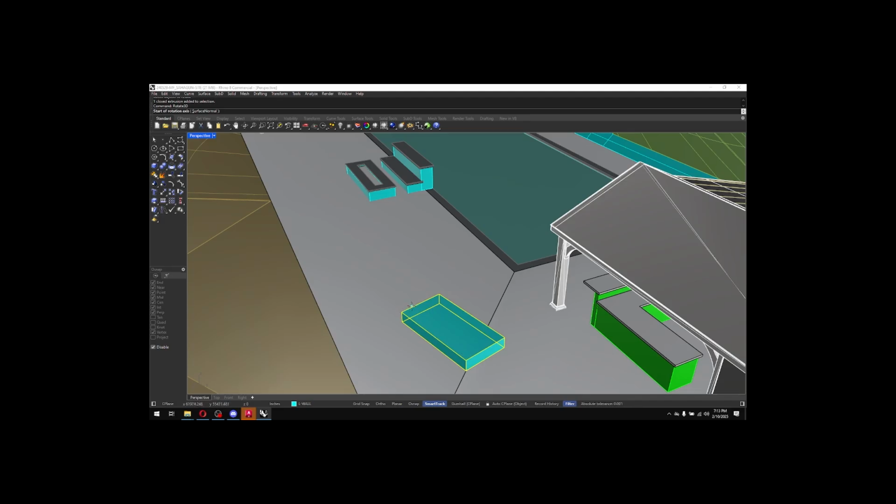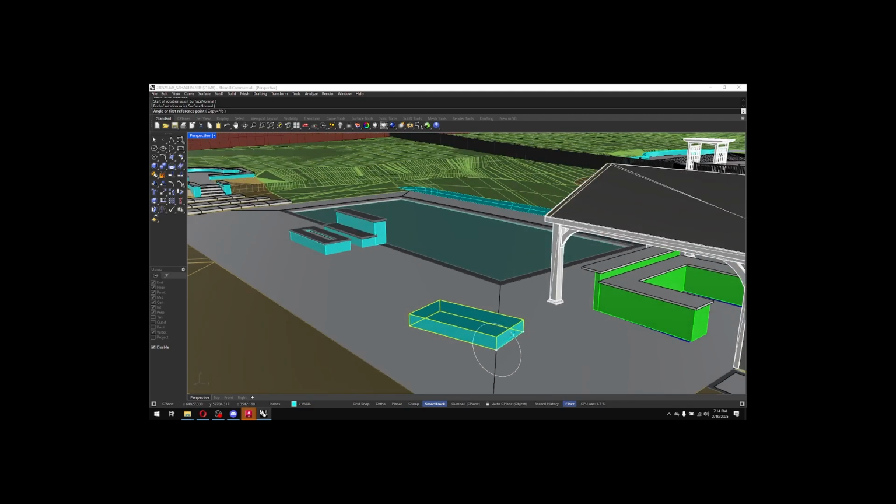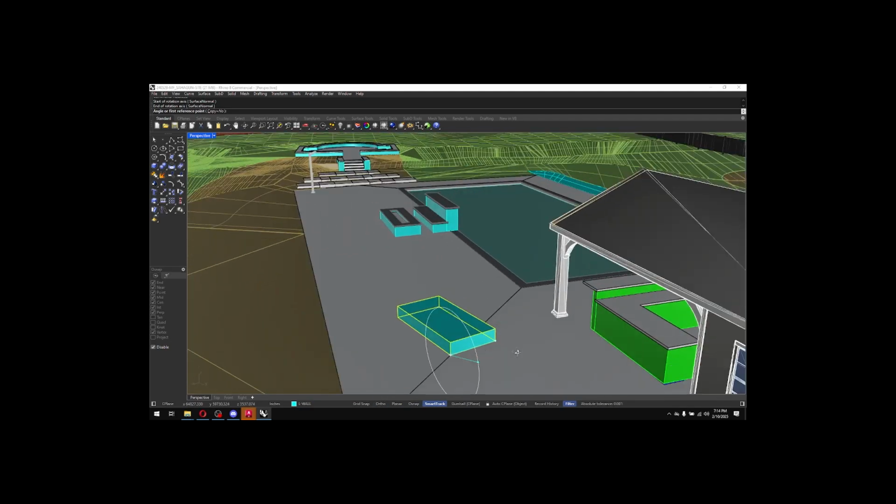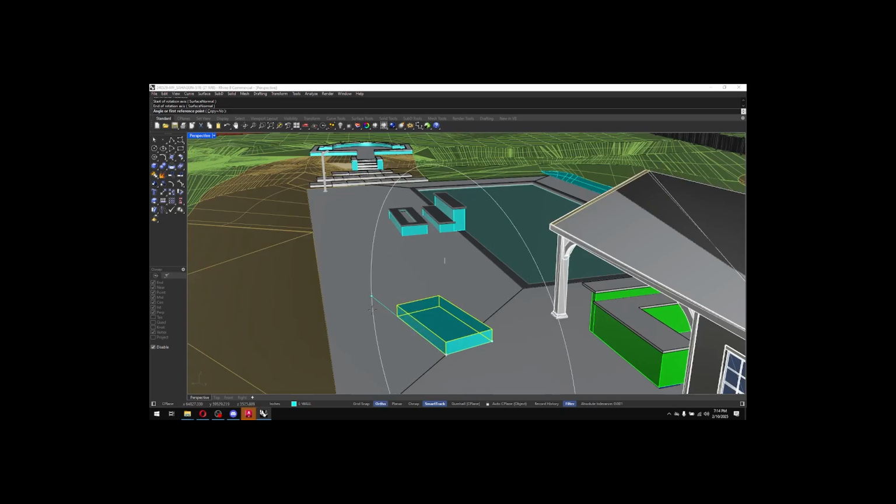If I want this edge to flip up, I need my steering wheel column to go perpendicular to that. So click there. Now you see your normal rotate circle, but it's going in the direction I want. So just hold shift, move my mouse so it's up, click again, and it's directly up. Again, you can type in your degree increments, all that kind of stuff. That one takes some practice, but again, just like the scissors and the paper, steering wheel column, steering wheel. That's what you're working towards.